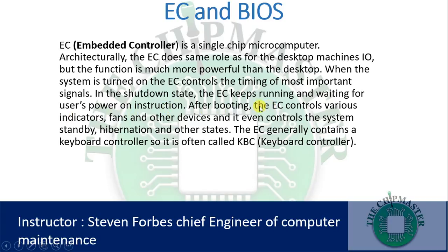After booting, the EC controls various indicators, such as the LED indicators, the hard drive LED indicators, the charging indicators, and so forth, the fans and other devices such as your audio, the keyboard, and so forth. It also manages the charging. It can also manage the temperature of the entire system. All of the thermal information is passed most times through an SM bus, which is connected to the EC. As I said, it controls the fan and many other devices. It even controls the system standby, hibernation and other states.